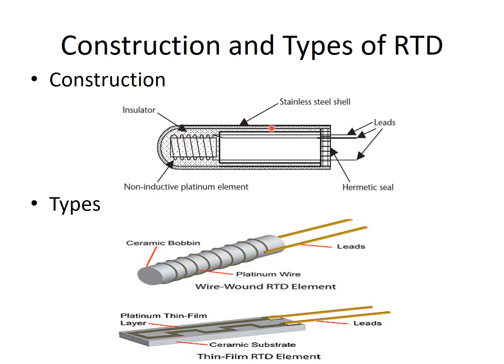Apart from that, we have a protective outer core for this RTD. We have insulators, a stainless steel shell, and non-inductive platinum elements. This is mainly to avoid corrosion of the resistive element. Usually the elements are enclosed in a protective tube of glass, depending on the range of temperature and the nature of the fluid whose temperature is to be measured. The tube is totally evacuated and sealed, or filled with air or another inert gas, and kept around atmospheric pressure, in some cases at high pressures.